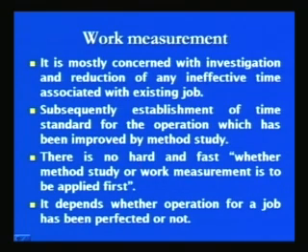There can be both types of situations where either the method study is carried out first or the work measurement is carried out first. Normally, for setting the standard of performance for a given job, method study is carried out first, so that the improved method is there, and subsequently work measurement is carried out.